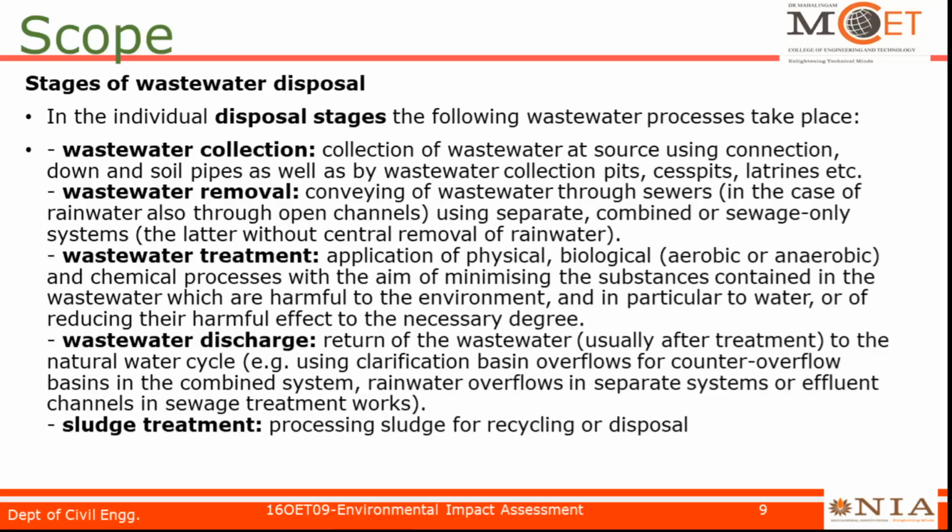Treatment involves application of physical, biological, both aerobic as well as anaerobic, and chemical processes. Aerobic uses bacteria which take up oxygen. Anaerobic uses bacteria which do not need oxygen, right? They thrive in the absence of oxygen. The aim is minimizing the substances contained in the wastewater which are harmful to the environment and in particular to water, or reducing their harmful effect to the necessary degree.